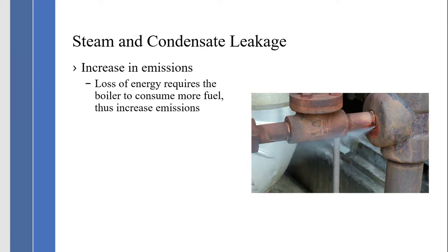The other thing is that it increases emissions. The more steam I leak to atmosphere and lose the sensible and latent energy, the more fuel I have to put in the boiler to produce the steam. So it increases emissions. So not only energy, we have to look at the emissions today.